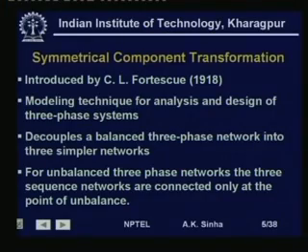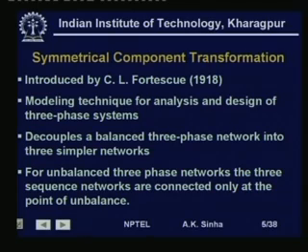How does it help? Well, symmetrical component transformation is a modeling technique for analysis and design of three-phase systems. As I said earlier, the advantage of this transformation is that it decouples a balanced three-phase network into three simpler networks. Means these three simple networks are not connected to each other, they are separated from each other, and therefore, there are no mutuals involved here. For unbalanced three-phase networks, the three sequence networks are connected only at the point of unbalance.